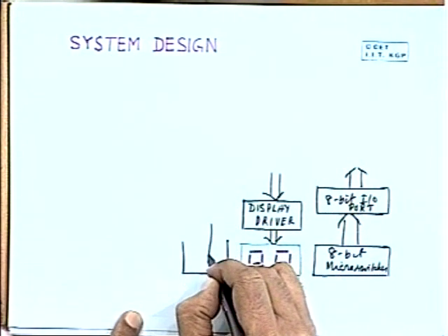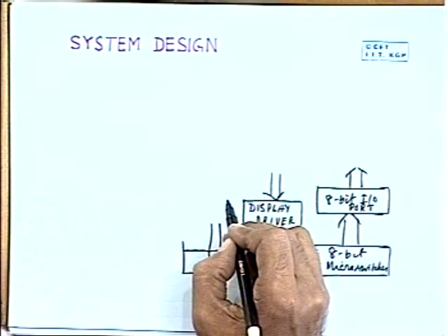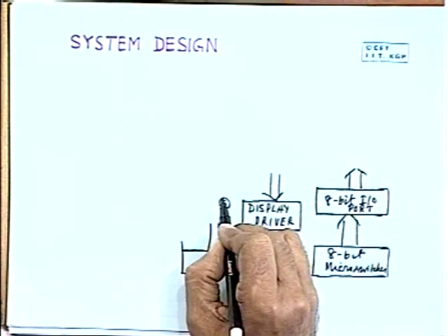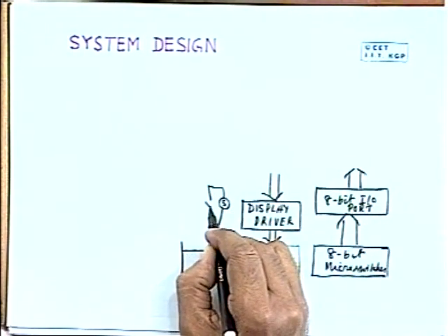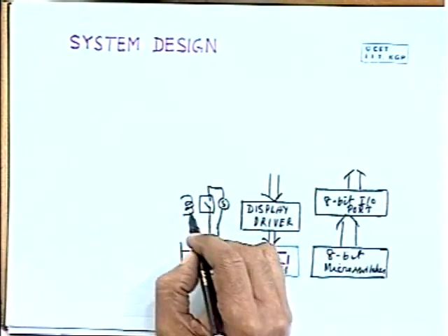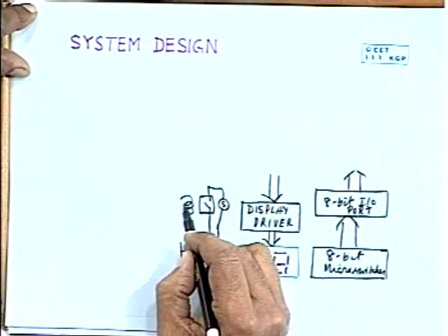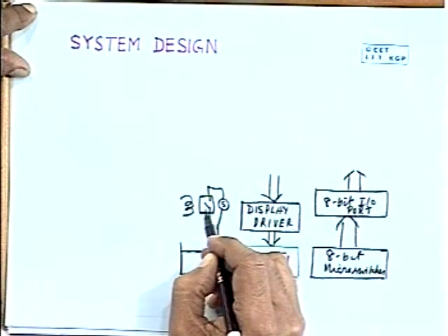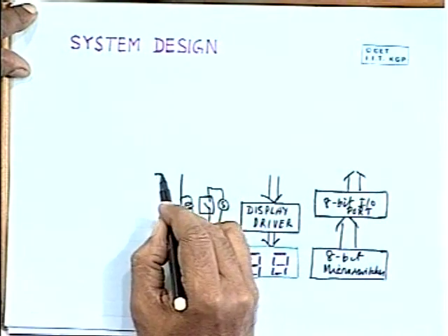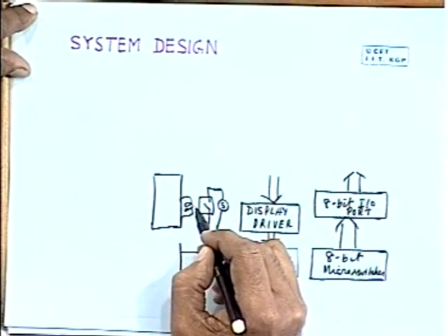and you have to use a heater to control the temperature of this water bath. And this heater has to be connected to the main supply, and the simplest way of doing it is to use a relay. This is a relay, and it can be controlled by a coil, and you know it's an electromechanical device. Whenever current passes through this electromagnet, this switch is closed or made off. So this relay can be controlled with the help of some driver. So you have to use some driver circuit to make this relay on and off.